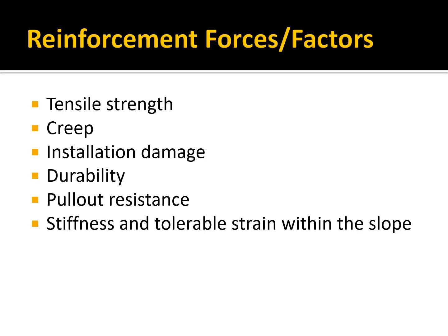How durable is the material? Is it going to corrode over time and lose its strength? What is its pull-out resistance? And how stiff is it, and how much strain will you allow in the slope? And in our previous video, we talked about reinforced earth walls. When they build those, they actually have them tilted a little bit towards the soil, and as the wall gets taller and taller as they construct it, it leans out a little bit. So they take into account the movement and the strain as part of the design.